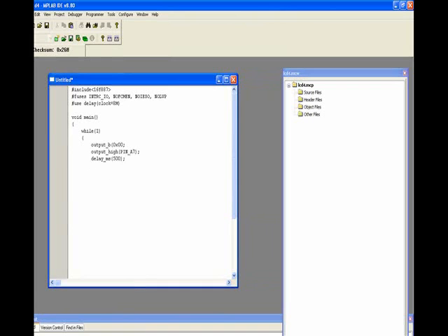What I'm going to do now is output low underscore low. Let me put my semicolon and go back. I will explain why. Output pin underscore 7A. Sorry, it should be a capital letter.